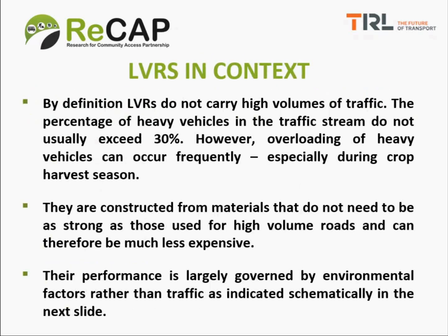Now, one of the key issues about low volume roads is that all roads carry a risk. The weather, the climate can be very adverse. The vehicles can be very overloaded and cause damage and so on. So, by definition, low volume roads do not carry high volumes of traffic, but they do occasionally have to carry heavy vehicles. The traffic stream will contain up to about 30% heavy vehicles on what we call low volume roads.